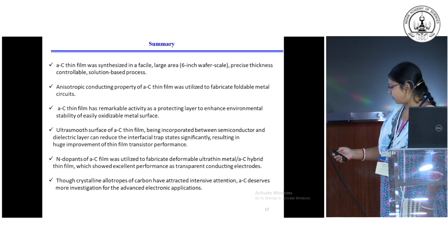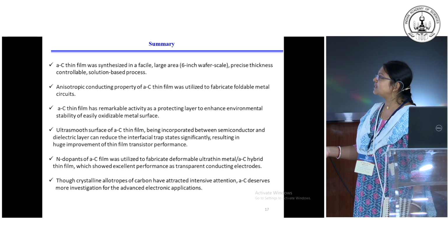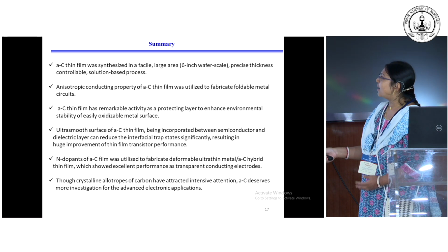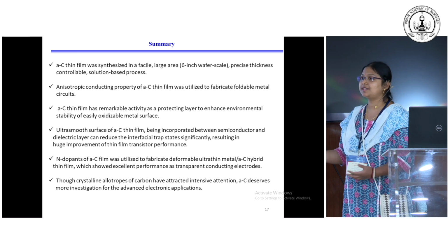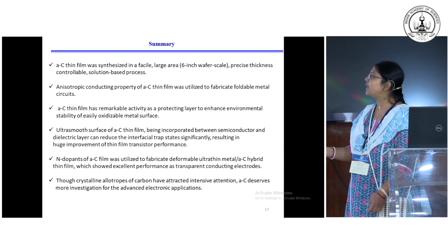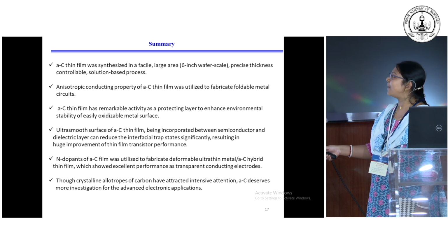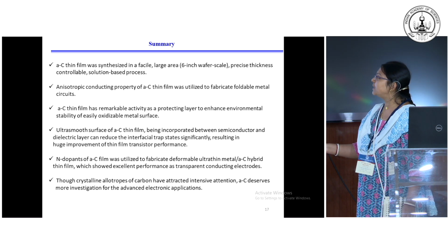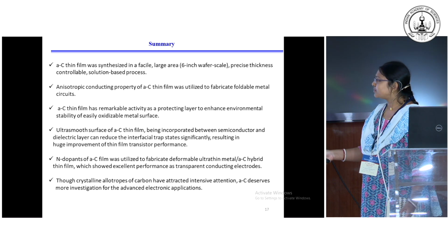So in summary, I have demonstrated that we can synthesize amorphous carbon thin film, by a very facile method, and in large area in 6-inch wafer scale. We can precisely control the thickness of the film, and we have utilized the anisotropic conductivity behavior of the amorphous carbon thin film to fabricate a foldable metal circuit.